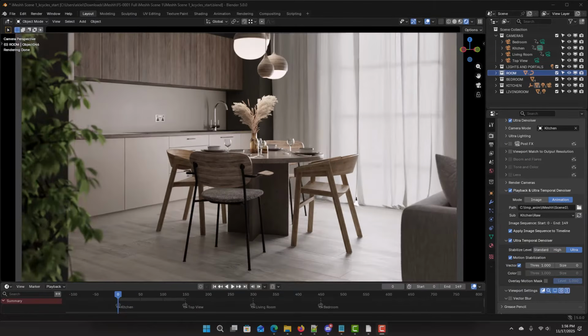To enable PostFX, we just select the desired camera image sequence and click on PostFX. You can use camera mode due to the fact that the camera bindings are tied to timeline location. When we load a different image sequence, it has a different timeline frame number, and then the camera will switch automatically, and we'll have camera mode effects, post effects for that sequence.